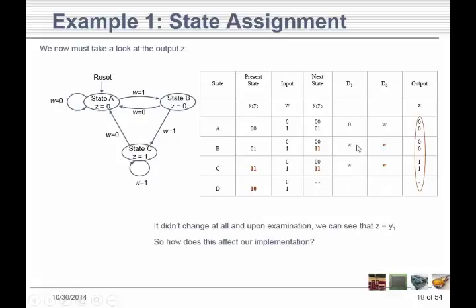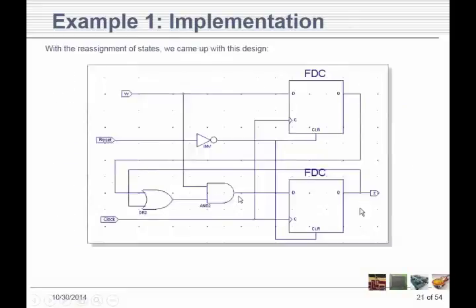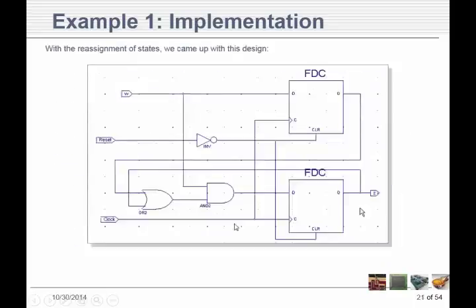So all that's changed in the circuit is this. And that changes from this design to this, which to me looks a whole lot simpler, right? I changed these from 3 gates to 2, and then I didn't need any of those inputs. All I needed was the W, so that became a lot simpler. So my point there is, look closely at the way that you count these. They don't have to.